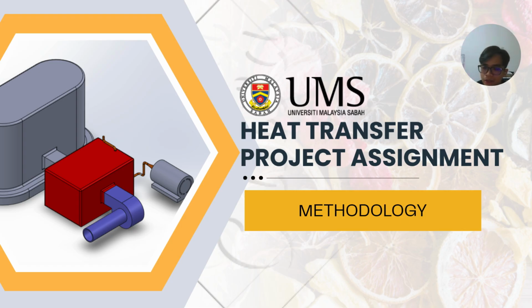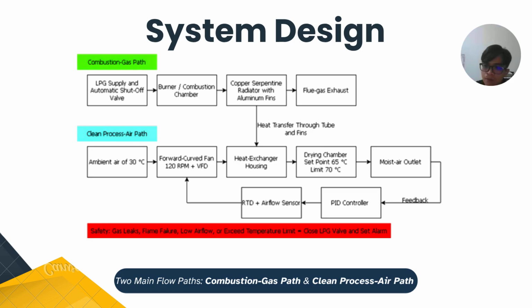Hello, I'm Alif, and I will present on the methodology part. So our work focused on developing a prototype scale indirect LPG fired air heater, which means the system was designed so that combustion gases do not directly contact the process air entering the drying chamber. And then, using SolidWorks Flow Simulation, we want to evaluate its airflow and heat transfer behavior.